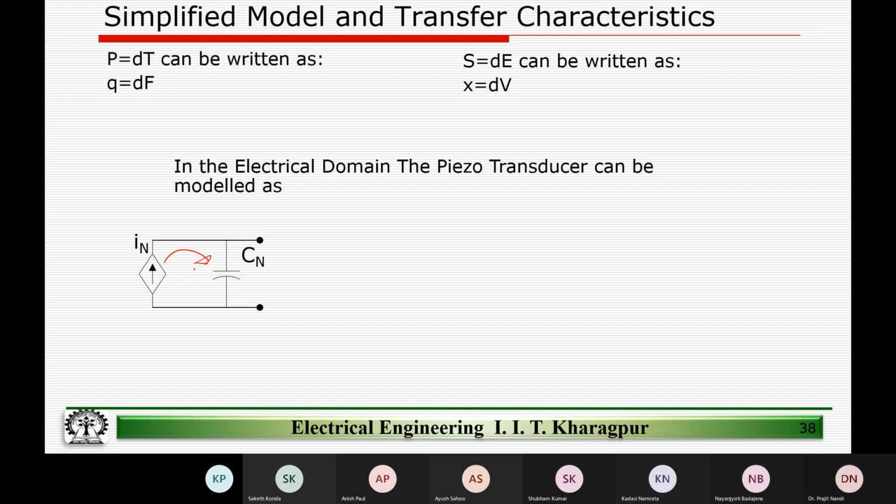So very simplistically, I am modeling the behavior of the piezoelectric crystal. When I apply a force, I get a charge, but force is a function of time, so similarly, charge is a function of time. Instead of writing this as charge, we cannot represent charge in electrical circuits, right? We have capacitor, resistor, inductor, current sources, voltage-controlled voltage sources, those kinds of things. We don't write charge anywhere, right? So how do we represent charge? We represent charge by having a current source in parallel with a capacitor, right? Not a big deal, right? Any questions on this?